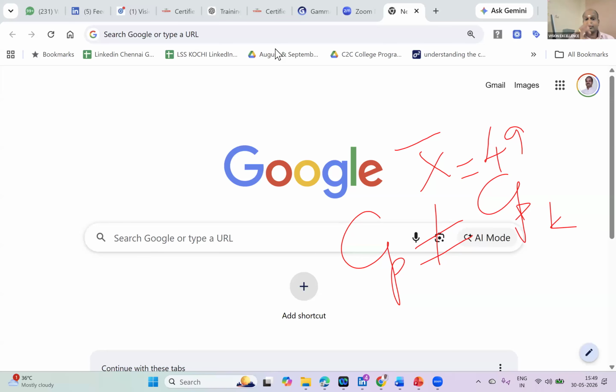Very good. But for calculation of standard deviation, the formula to be used is R bar by D2. And R bar is nothing but the center line in your R chart. D2 is a constant that depends on your sample size. This much, all of us know.